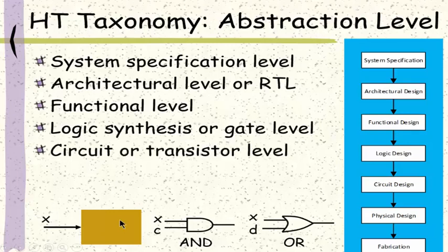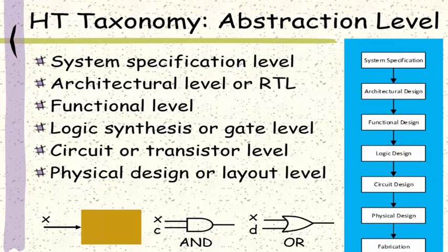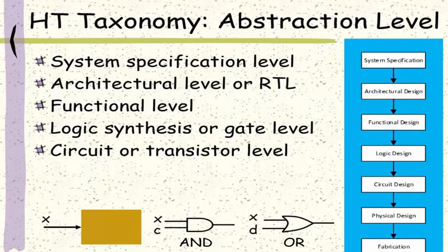At transistor level, there are also many ways to insert hardware Trojans. For instance, some physical parameters such as threshold voltage or transistor size can be changed to impact the delay of the logical gates, the power consumption of the logical units, or the aging process of the transistors. These timing or power features may leak information or facilitate side-channel attacks.